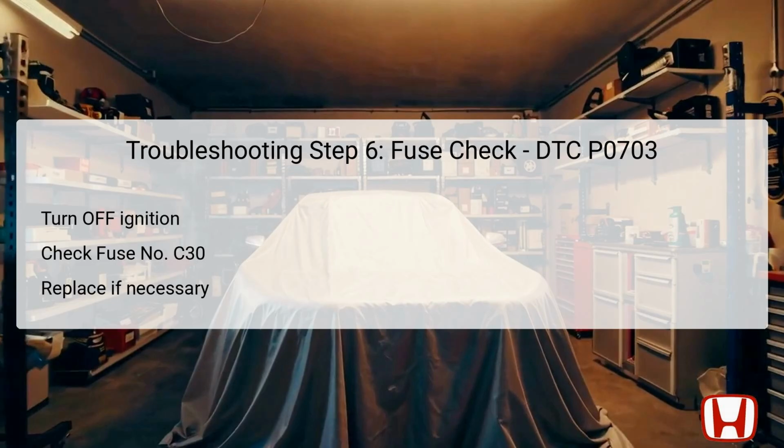If the fuse is in good condition, it indicates that the wiring leading from this fuse to the brake pedal position switch may have an open circuit that needs to be repaired. However, if the fuse is found to be blown, then it will need replacing. While replacing the fuse, it is also advisable to inspect for any potential shorts to ground in the circuit related to the C30 fuse, as this could have caused the failure originally.